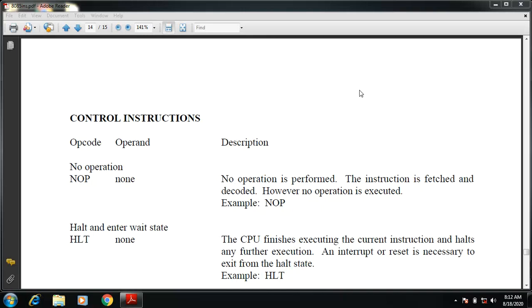And it also includes push, pop, input, output instructions. These instructions I have already explained. Data transfer, that is push into the stack, pop from the stack, exchange top of stack with HL register pair, copy HL into stack pointer, read from input port, and write to output port. So these instructions are already explained.